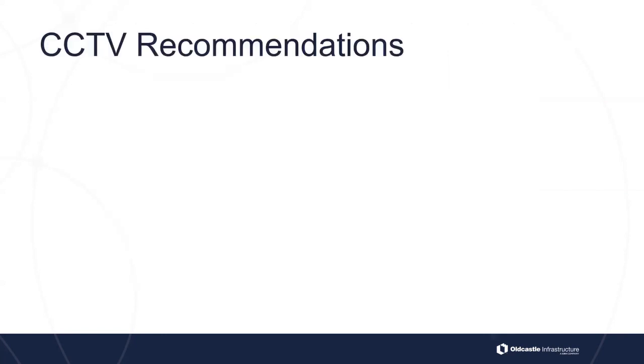So let's talk about the recommendations for CCTV. We want to make sure that we're getting the best inspection possible. So let's look at what that means. One of the recommendations that I've tried to get people to write into their specifications is that for any post-installation inspection videos done with CCTV, the person operating the machinery is NASSCO PACP certified. NASSCO is the National Association of Sewer Service Companies, and PACP is their Pipeline Assessment Certification Program. We want to make sure that whoever is doing this is PACP certified.